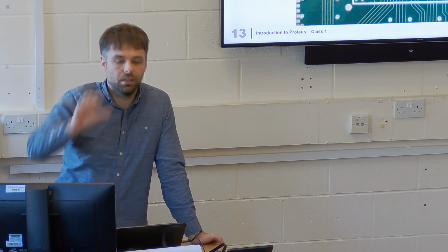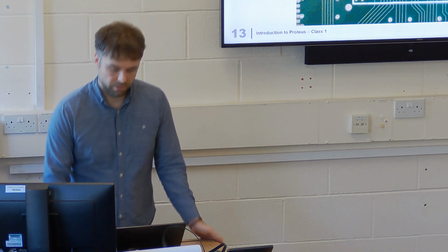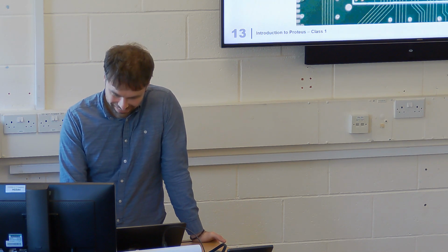What's the current limit on those? The number of layers you can do in this type of technology then? There are some boards of 36 layers. So the current limit would be determined by the copper thickness of each layer. And you can essentially double up or use multiple vias to increase current as well. But in terms of layer count, you can get up to 36 layers on these boards, and maybe even more in certain circumstances. But it's just crazy. We're not going to start with 36 layers.